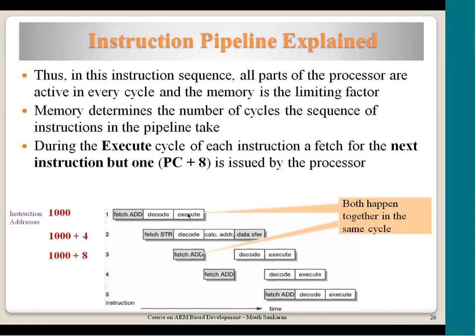So if the programmer assumes that when the add instruction or whatever is getting executed, R15 is pointing at its own address or the next instruction, it is not true. R15 will be pointing at the second instruction from the current instruction getting executed. So any dependency on R15 in the assembly code needs to comprehend this pipeline effect during programming.